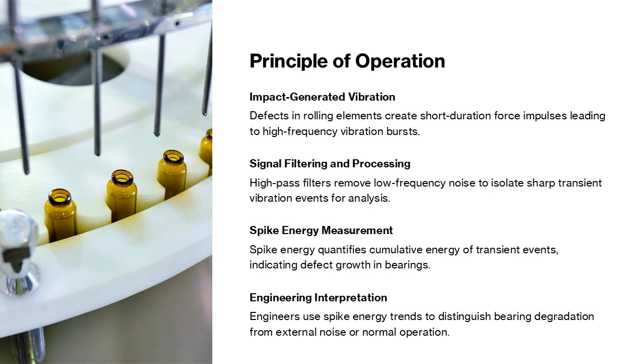From an engineering standpoint, the method assumes that defect-related impacts are the dominant source of high-frequency spikes and that their energy content increases as the defect grows. This assumption generally holds for rolling element bearings under steady operating conditions. Understanding this principle helps engineers interpret spike energy trends correctly and recognize when increases may be related to bearing degradation rather than external noise or process-related impacts.